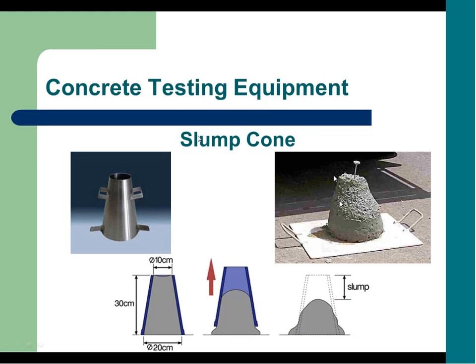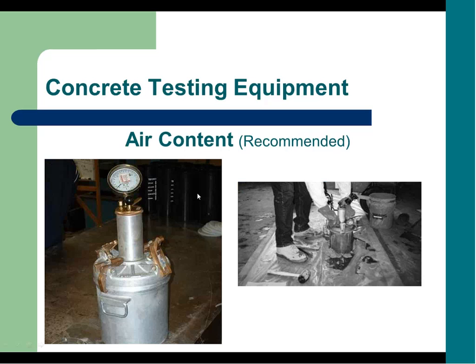You can also see in the picture of the already formed concrete that temperature is taken. That also tells a lot about how that concrete is going to react when it's in place. Air content is recommended to be done. If air entrainment is prescribed or required in the mix, I would suggest doing an air pot test.